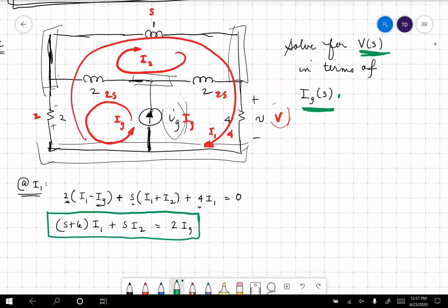Mesh analysis will lead to nicer equations because you're multiplying versus dividing by impedances. Nodal analysis, typically you have to clean up. You're dealing with functions of S, and they start to get ugly. With mesh analysis, notice how nice this equation popped out. It was really simple and pretty quick. But you still want to use the technique that uses fewer equations, because that is going to save you more time in the end.